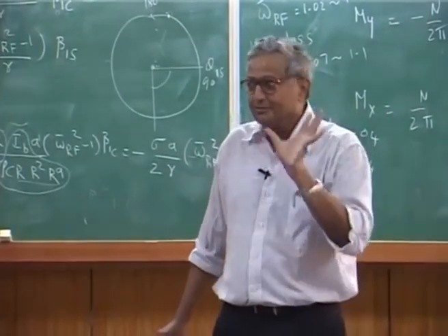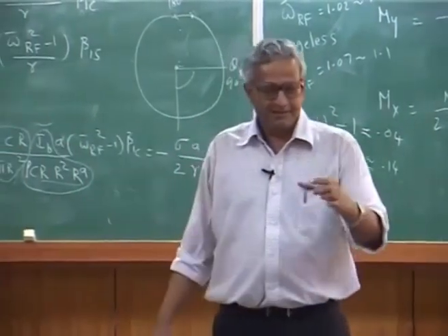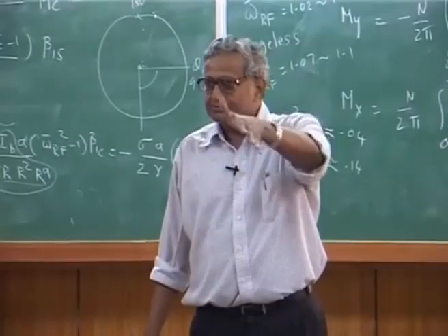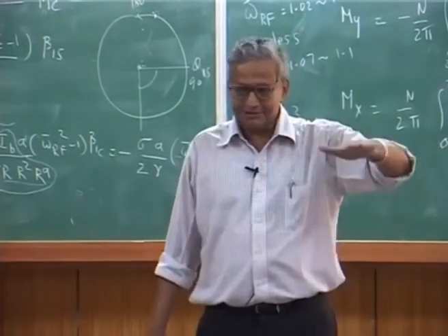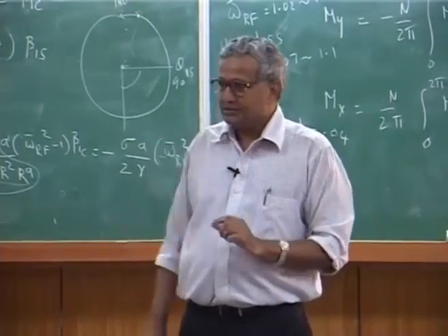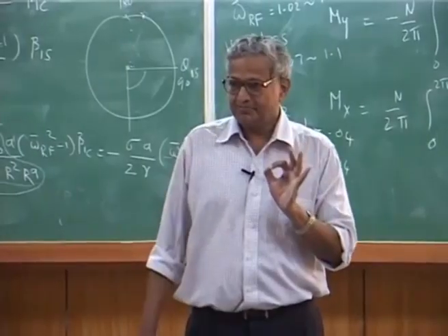Now you add aerodynamics, that is like you are having the airfoil. If I tilt, you see it will immediately come. The time it takes for the rotor to respond is very quick, particularly in flap motion.